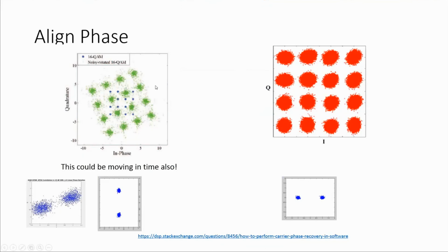That's the phase align. These are all coherent modulations, which basically means the phase matters. This is a 16 QAM, and this is a BPSK. So the other thing you can say is if I have QPSK, it's just two BPSKs that are in quadrature. So if I stick this on top of here, I can double the information rate with the same amount of power.